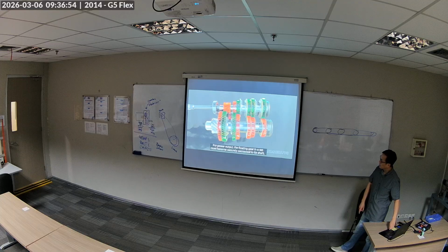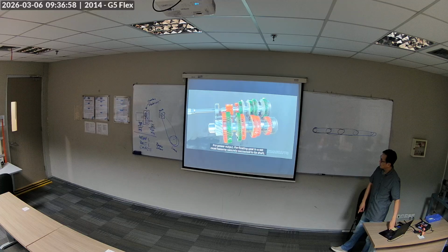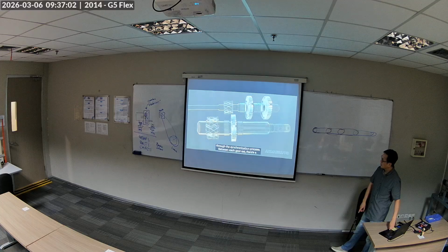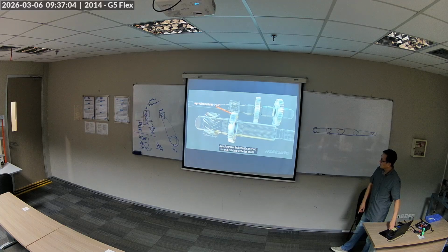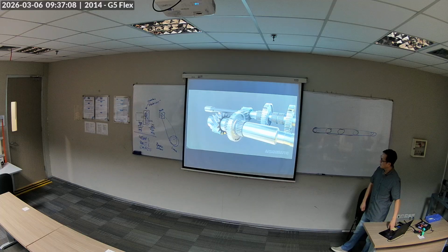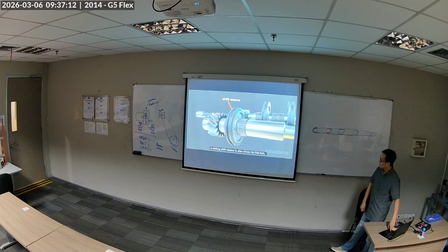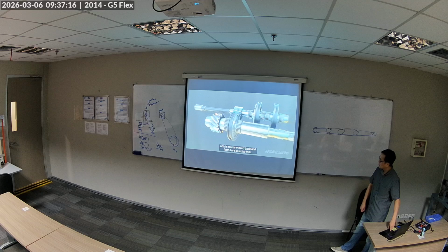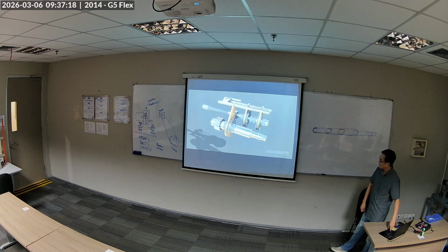For power output, the floating gear in each set must become securely connected to the shaft through the synchronization process. Between each gear set, there's a synchronizer hub that's splined to and rotates with the shaft. A sliding shift sleeve is also driven by this hub, which can be moved back and forth by a selector fork.